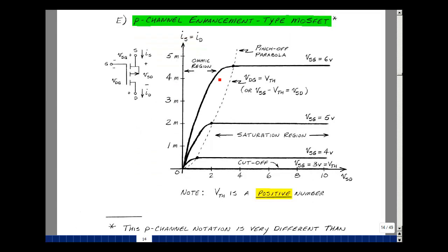If there's an N-channel MOSFET, we could find a P-channel MOSFET by using a piece of N-doped silicon and inducing a P-channel. I drew this upside down because in electronics we show current flowing from the top to the bottom of a schematic. And every voltage and every current is going to be reversed because we're replacing P material by N material by P material. The current is entering the source coming out of the drain. These two are equal to each other because the gate current is still 0.